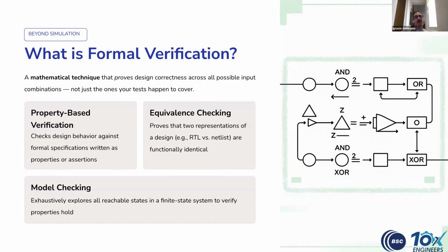Another verification methodology is formal verification, as we mentioned. Formal verification, instead of simulating with test vectors, uses mathematical proofs to exhaustively verify a property of the design.